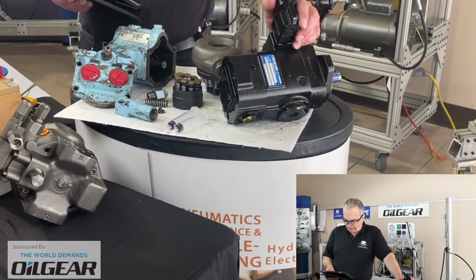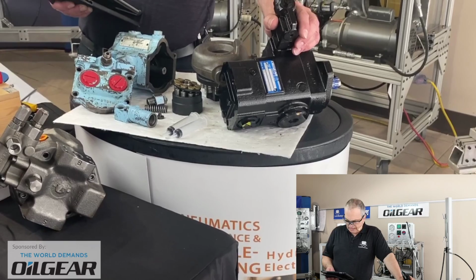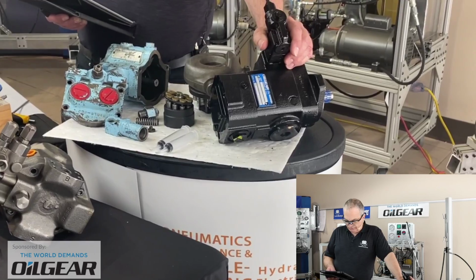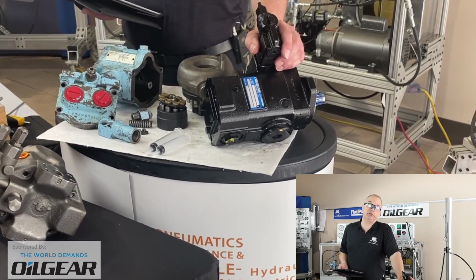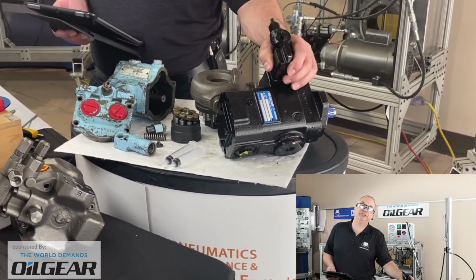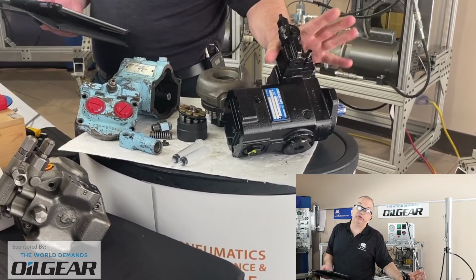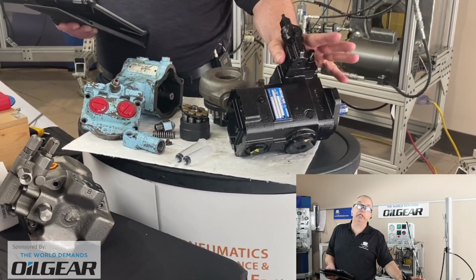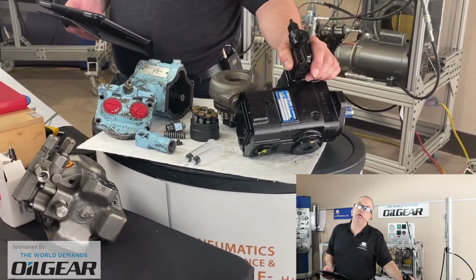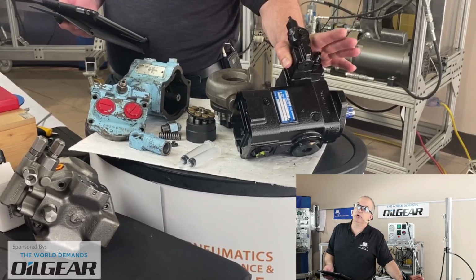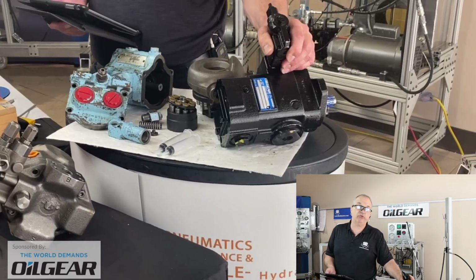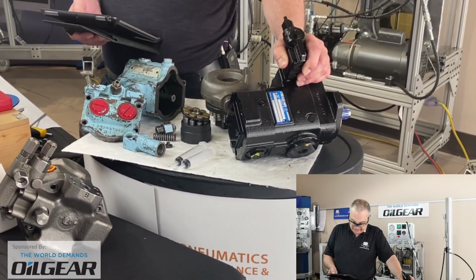Let's see here. Samer's asking, do you think for the Rexroth A10V that you have to have pressure cutoff there? And perhaps there's no need for a system relief valve. Yeah, there are certainly hydraulic systems we bump into where the user is very confident that there will be no pressure spikes, and by user I mean the hydraulic system engineering group, who are ultimately responsible for the safe design of the system. If they're convinced there will be no pressure spikes, then I do occasionally run into systems that have no relief valve together with the use of an A10V pump. So yes, that does happen.